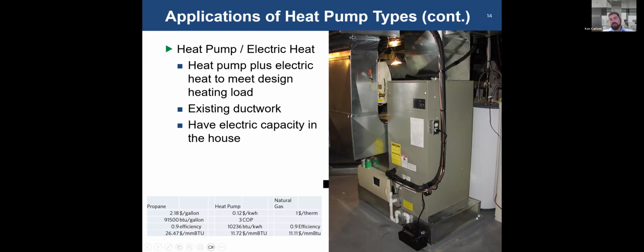But the electric resistive heating does draw quite a demand. It's typically a higher capacity because it is resistive heat. You do need to evaluate the electrical service and whether or not you have enough room in the panel to actually run a new circuit for this.